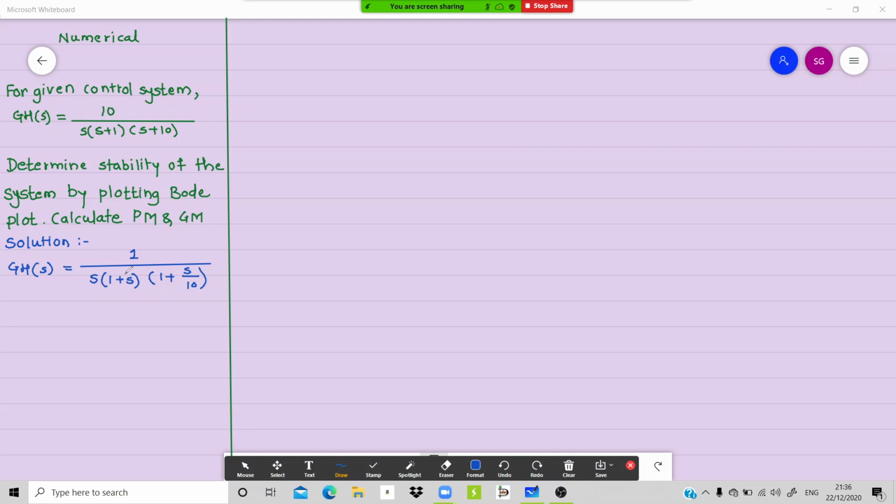So we are trying to get these things in the form 1 plus j omega by omega naught, which we were interested in. If you remember the thing which we had solved, we were interested in the cutoff frequency over there. The same thing we are trying to achieve over here. Then we'll write this in terms of S equal to j omega.